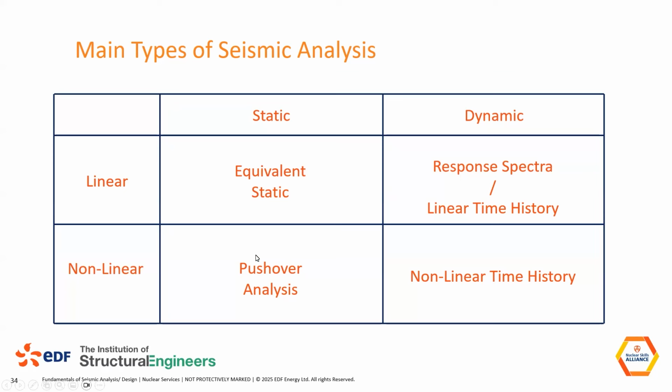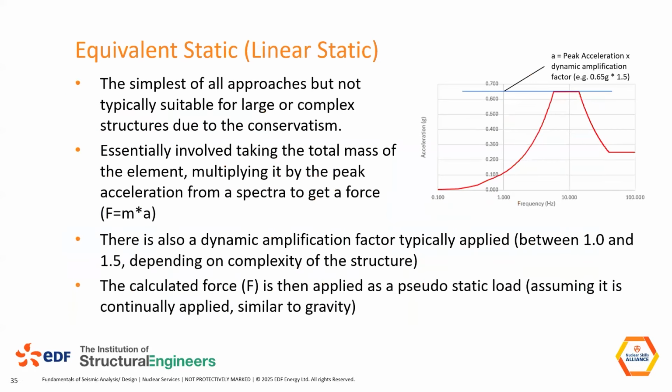So if we talk about, just briefly, I've got one slide in each of these, I think, just to cover it. We'll start with the equivalent static, which is the simplest of them all, but is quite conservative. So in this case, we are taking an earthquake and representing it by a set of static forces. And then we can just analyze them the same as any other static force, the same as dead load, the same as wind load. I mean, wind load's not static either in reality, but we treat it as a static load, except for tall buildings. Anyway, sorry, I'm going off track.